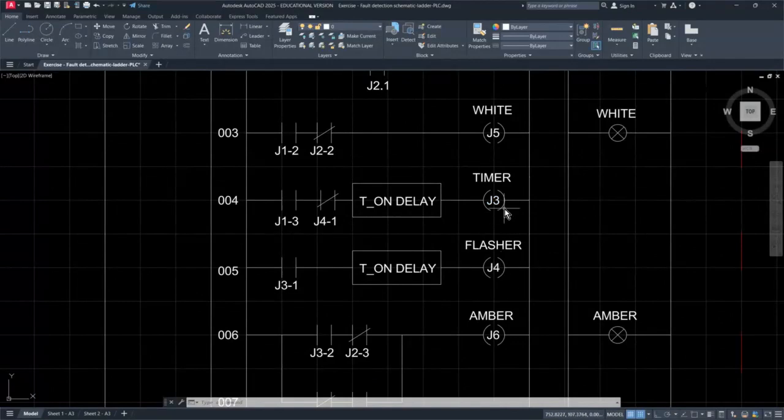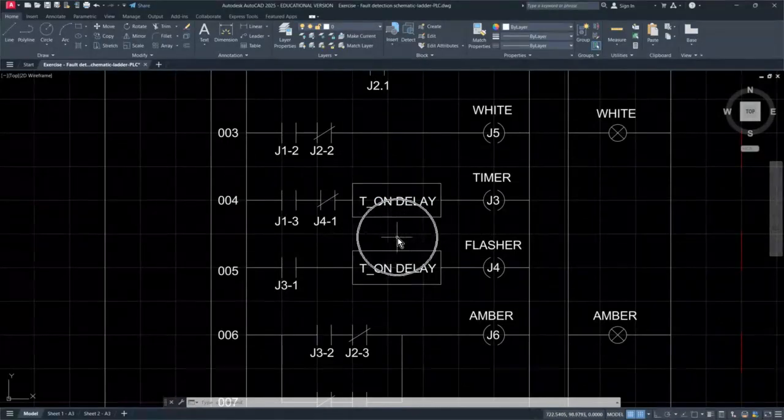Those are internal relays, so they're not external, they're internal. They don't cost anything. You can put as many as you want. There is a limit, but the limit is pretty high for each PLC, so you're not going to exceed it with a simple program like this. Basically, 1 timer gets activated, and after the time delay it activates a timer which turns this on. This timer gets activated, and when it's deactivated, it turns this one on. So they basically activate each other with the time delay. They click one, another, and they just oscillate between the 2. So that's how that system works.